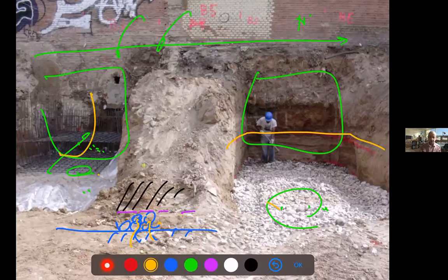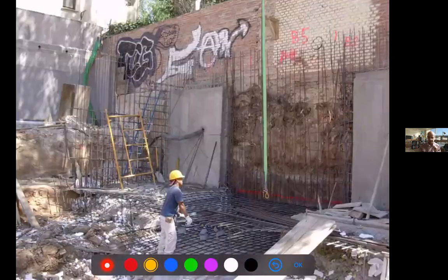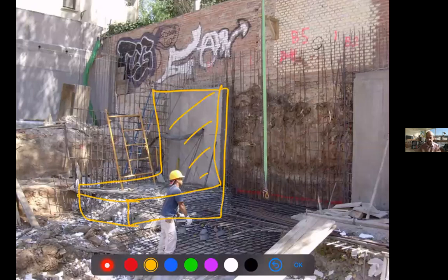So once you have these walls, that part is retained, you can excavate the rest, and then there's less danger. It is not always possible. You see, this kind of sand is very good quality, very solid, very dense, and it works okay. And it's okay for small basements, right? In larger, deeper basements, you have to be more careful. So once those walls are done, and you see that it is almost 1-to-1, so it has stability by itself, then you do the rest.